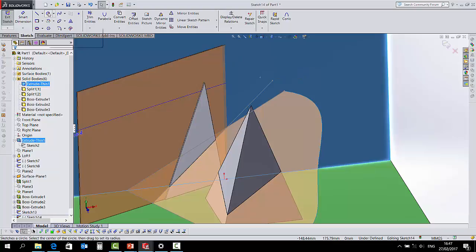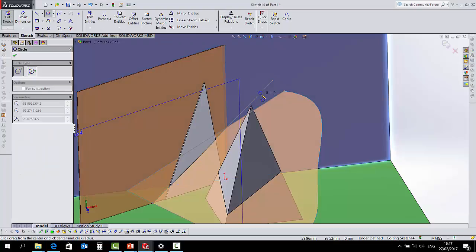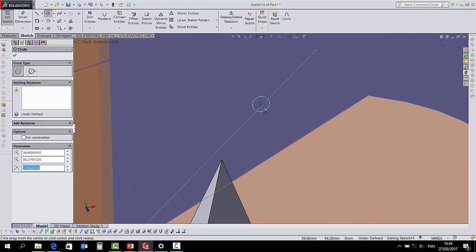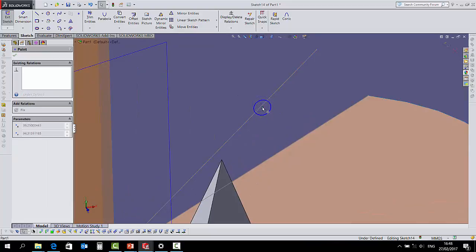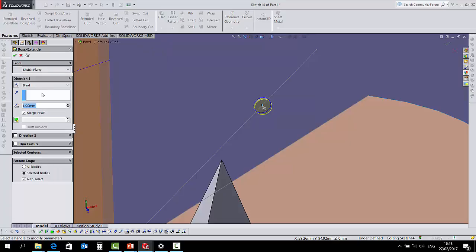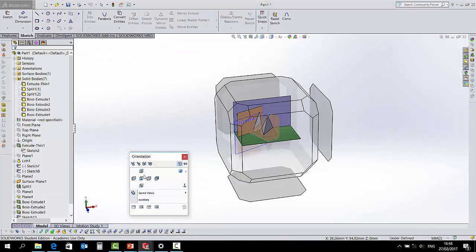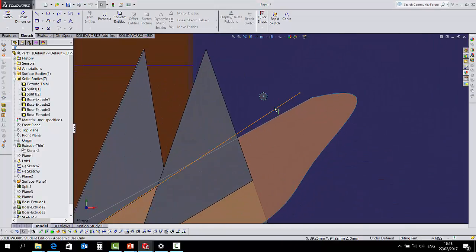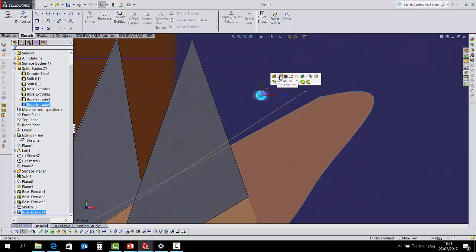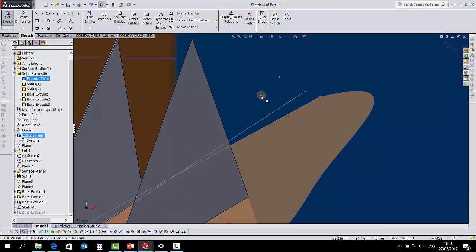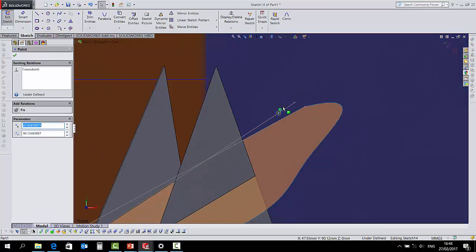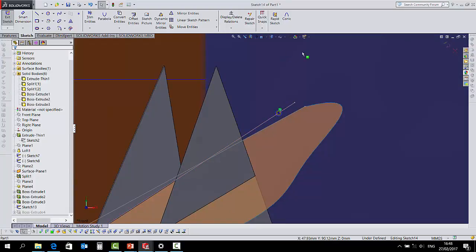I'm just going to take a point on the line here, like so. There's where my point P is going to be. And this is features, extrude it out. Don't merge it. There's our point P on the plane, as I would look in the front. Oh no, pardon me. Edit sketch. There he is on the vertical trace of that. You can see there's P, like so.